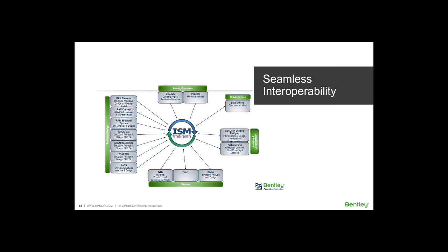You can do the analysis in StatPro, and if there are any changes in the member sizes, you can bring back those changed member sizes back into ProStructures. So you don't need to come into ProStructures and remodel or modify those members. The updated model that you bring in from StatPro will already have the updated sizes, right?